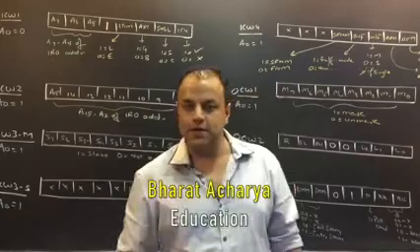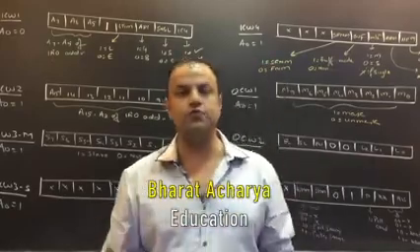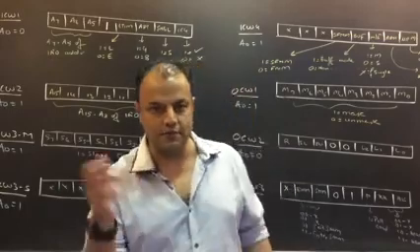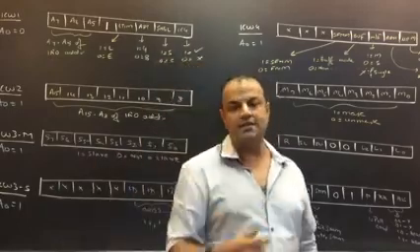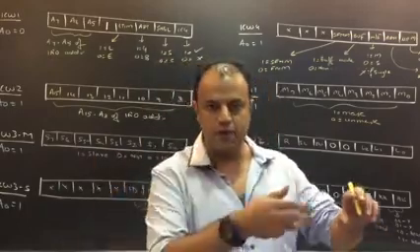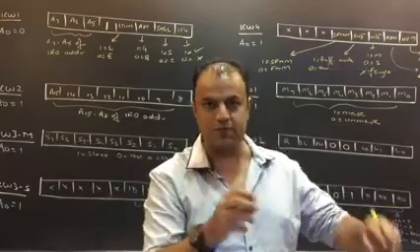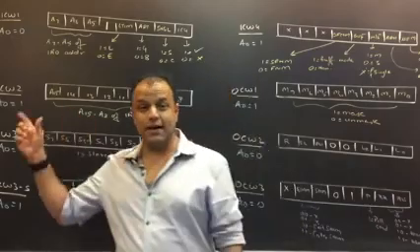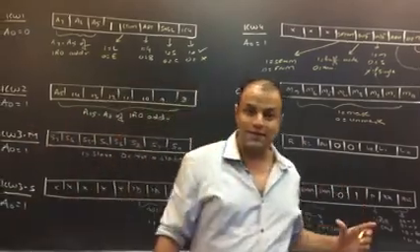Now, you have the background of 8259. It is used to increase the number of interrupts. The first thing that you need to do is initialize 8259. For that, you need to give these commands. These commands are given by the programmer to 8259 through the data bus of 8259. Now, that data bus is 8 bits. That is why all of these commands are 8-bit commands.